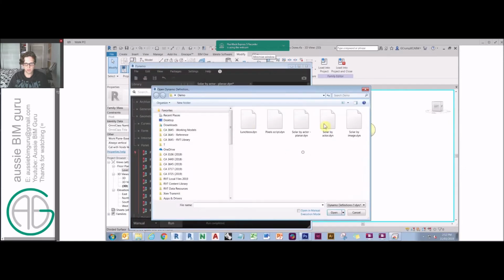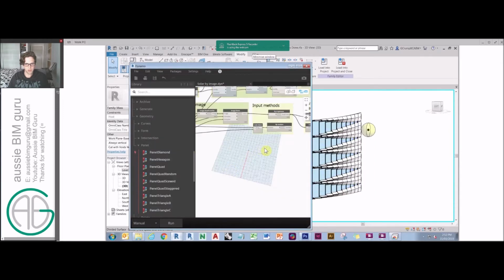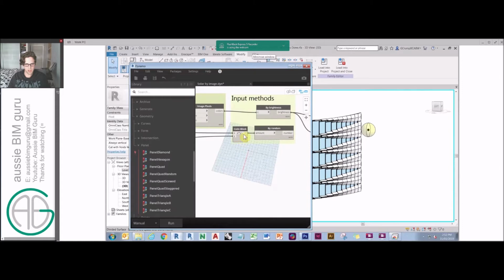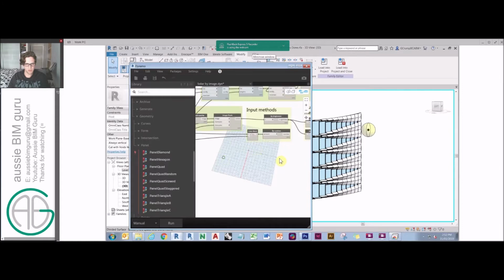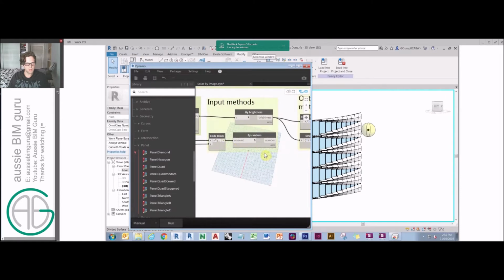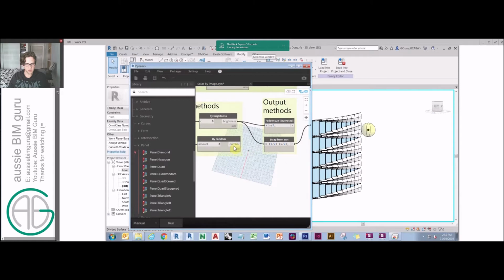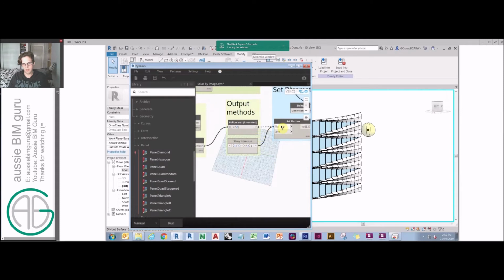I'll just go back to my solar by image and use my randomized function instead. So I'm basically taking a number of random samples, basically 15 by 5, so I want one sample per curtain panel. And from there I can feed these into a divisor just to half the values in principle. So just to save a bit of time, I might just do the pure divide by 2 because it's all random, so who cares what number it's being related to at this point, purely random.